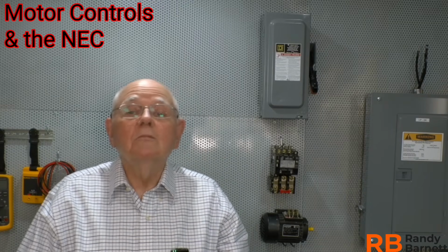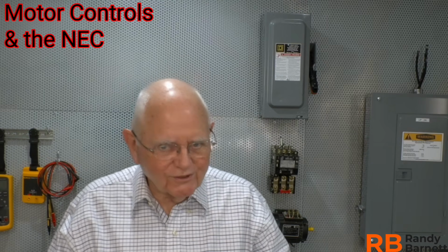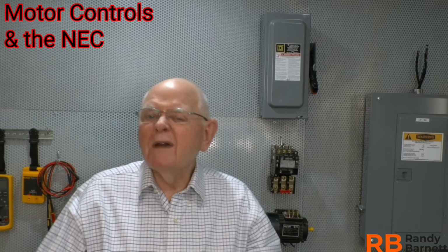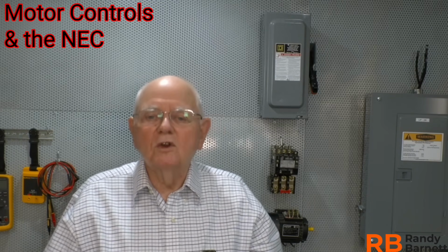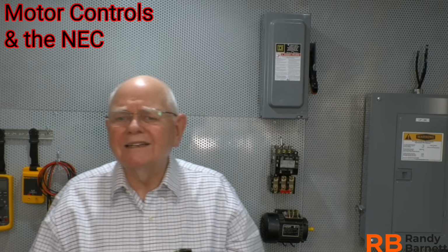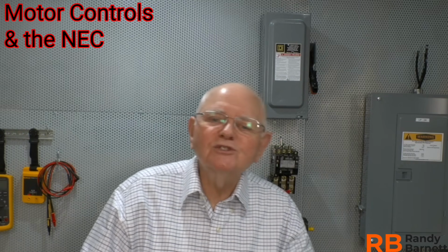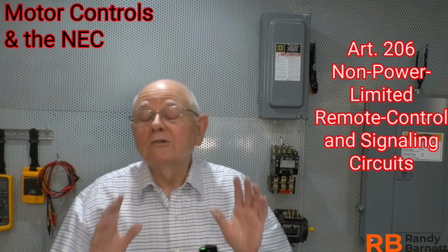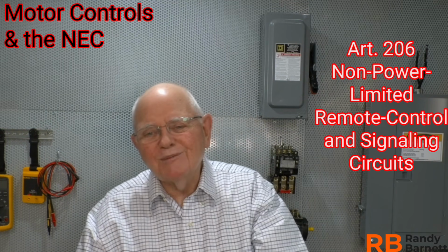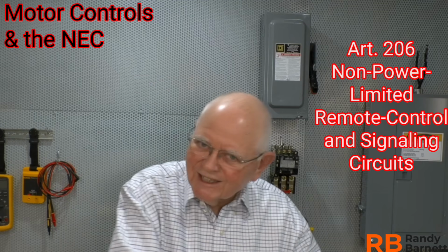Today we're going to talk about motor controls in the National Electrical Code, the NEC. Specifically, we're going to talk about what we probably most commonly run into out in the field, and that's control circuits that are not power limited in any way. For the 2026 NEC, we have a new article for that situation, and it's Article 206, non-power limited remote control and signaling circuits.